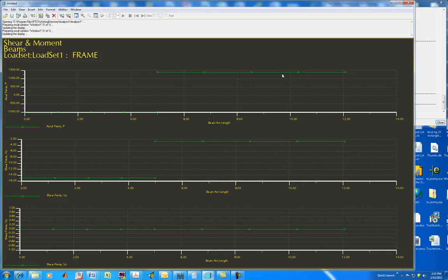That's very reasonable. Shear force in the Y direction on the lower beam is constant and tiny, and shear force in the Y direction on the upper beam is virtually zero, and shear forces in the Z direction are zero. That would make sense on all of these.